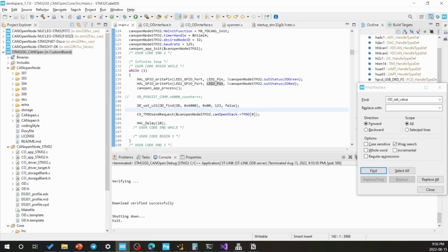And just one quick note here is that we don't have this observation here. In some stacks you have something we call COS trigger, change of state trigger, and in those cases the stack will basically monitor a value and then transmit it when it changes. But we don't have that in CANOpen node because regarding the standard for CANOpen, it shouldn't do that. So it was an extra thing others implemented. If you want to implement that, you should consider it in your code.